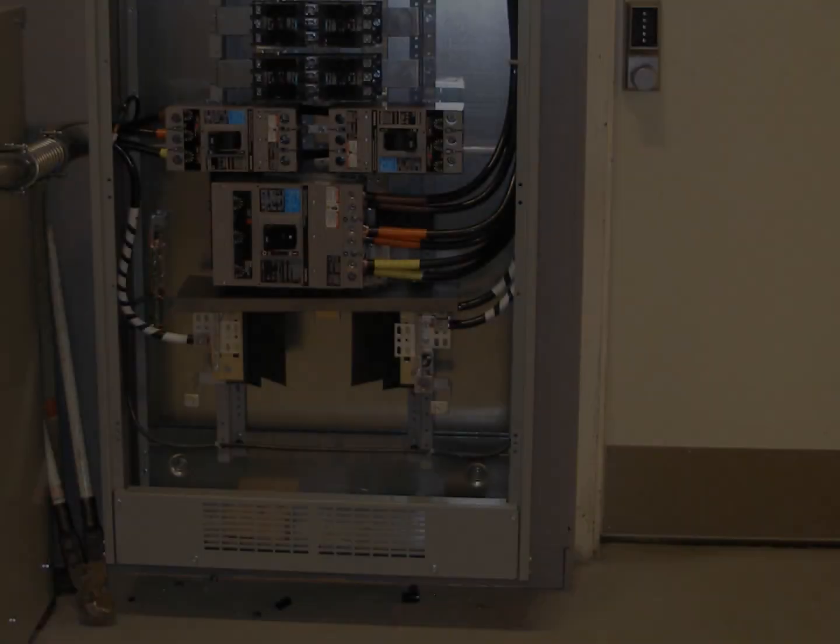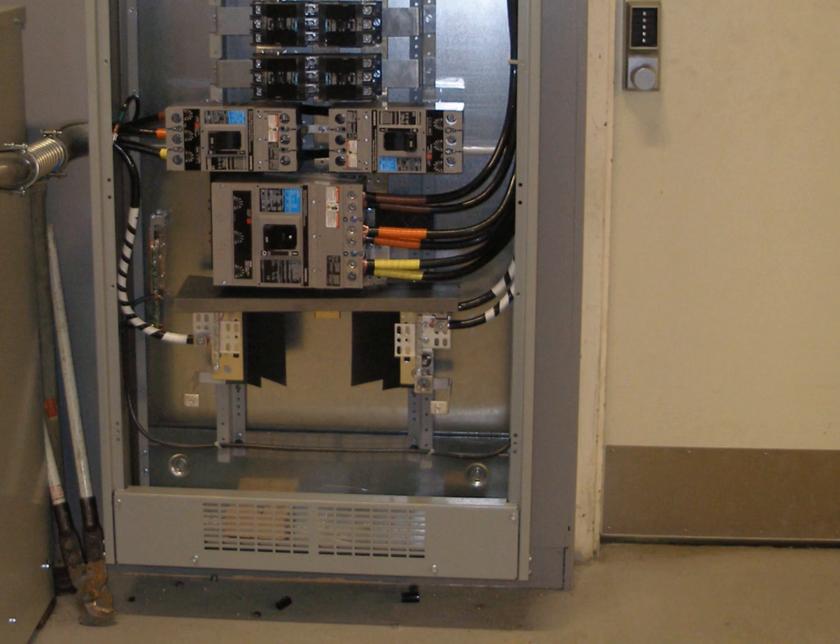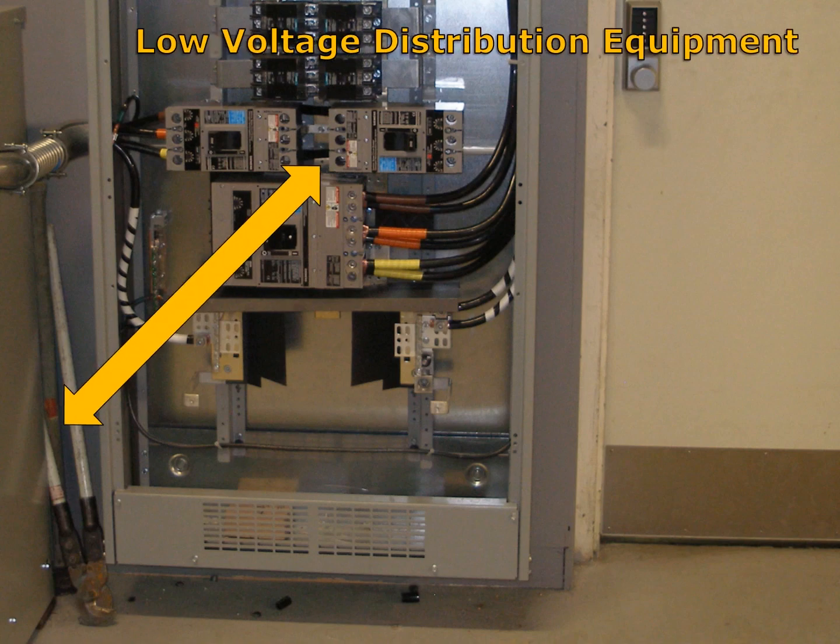IEEE 1584 references 3 different working distances depending on the type of equipment. These working distances are typically used as part of arc flash studies. So, for example, for low voltage distribution equipment, the working distance that IEEE 1584 lists is 18 inches.